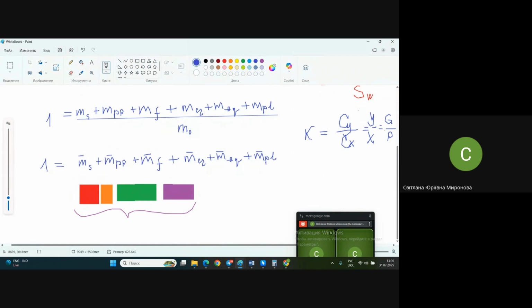Yes, and out of this thing, knowing your aerodynamical quality, it's already known what is the necessary, approximately, at the first approach, at first iteration, what is the approximate value of thrust you need to support this weight during cruise flight. And you may go into reference books, into the market, wherever, and check what engines you have, what propositions of engines you have.